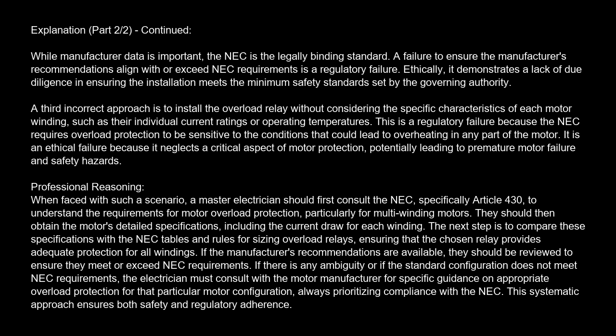This is a regulatory failure because the NEC requires overload protection to be sensitive to the conditions that could lead to overheating in any part of the motor. It is an ethical failure because it neglects a critical aspect of motor protection, potentially leading to premature motor failure and safety hazards.